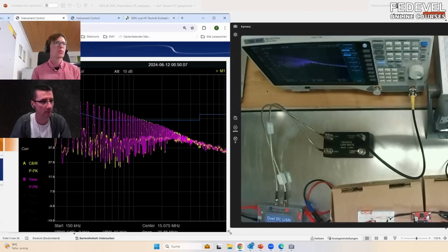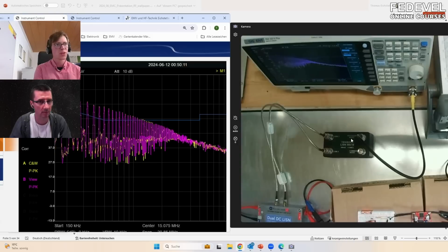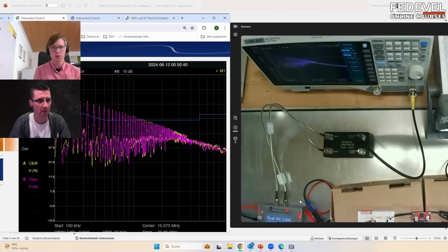My device here on the input is not in such a big danger, because when you don't have this attenuation here, this means strong interferers can go directly into the device and damage your analyzer. You can also add your limiter for additional security. But in my setup, I have no big interferers, so this 10 dB would be enough.